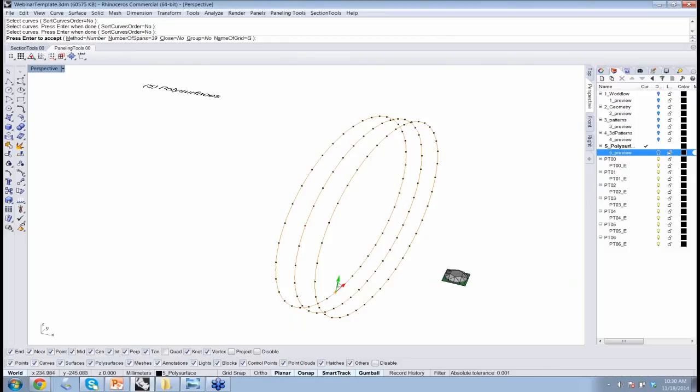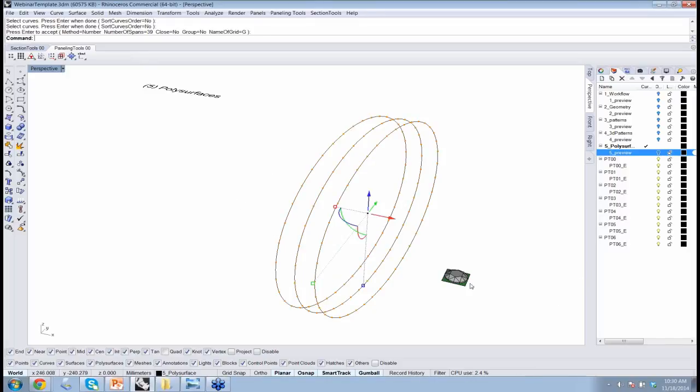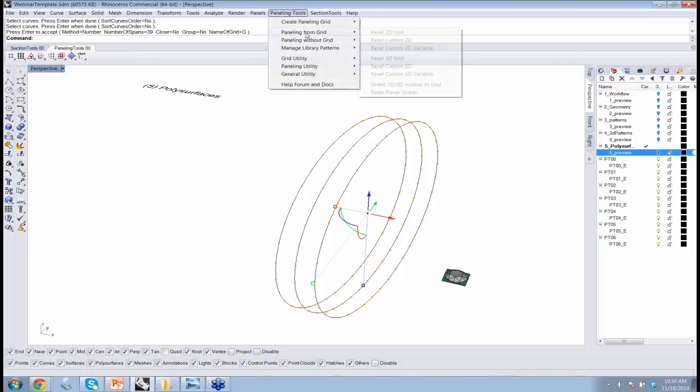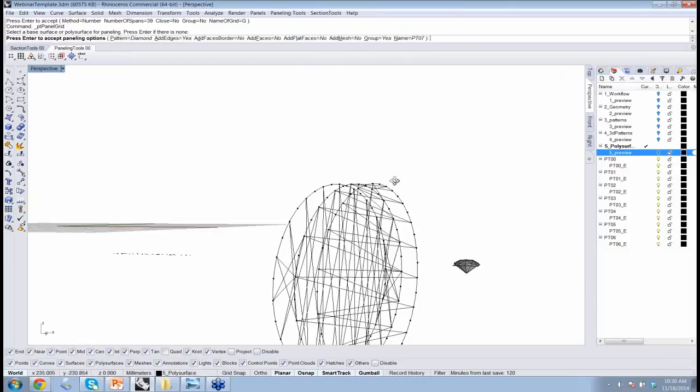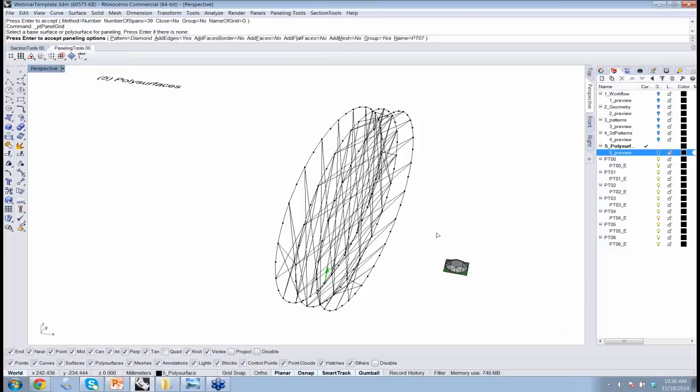If you look at the arrows here, it shows me that the red one is going in the predictable direction. So this is my row direction. But if I look at the green arrow, I see it going up. I would have expected it to go across, because that would be the V direction. So I immediately see there is something a bit fishy about this kind of grid. I'll commit it anyway, but before I populate my stone, let me just run a quick panel 2D grid to see how a box kind of grid will look. Now look, it looks very, very messy.